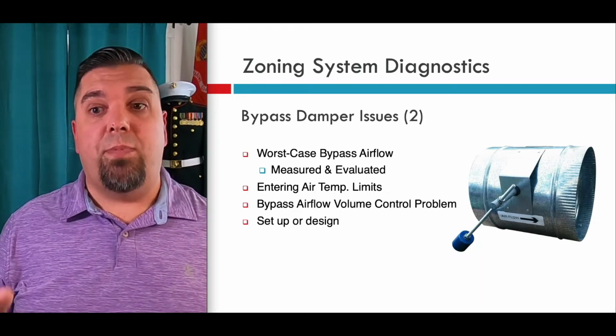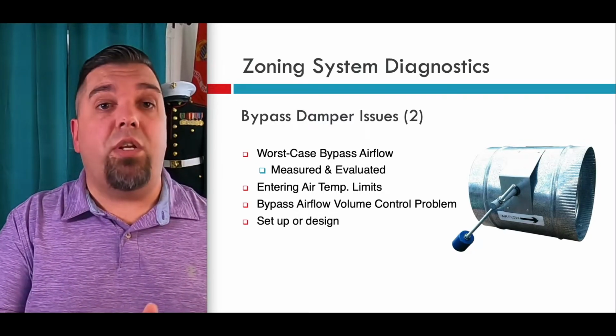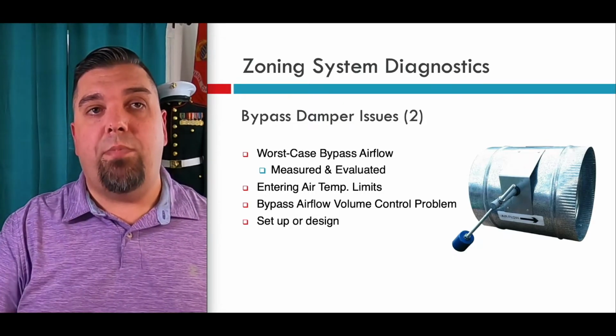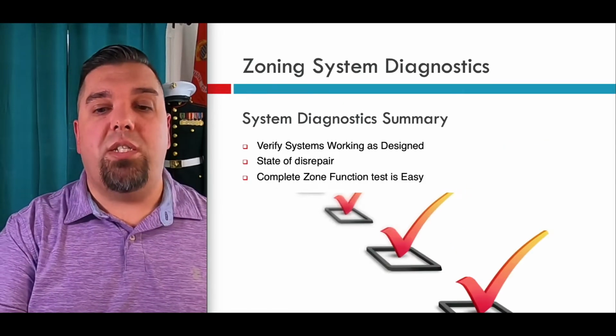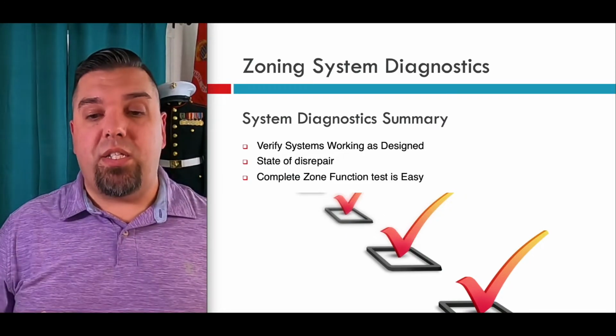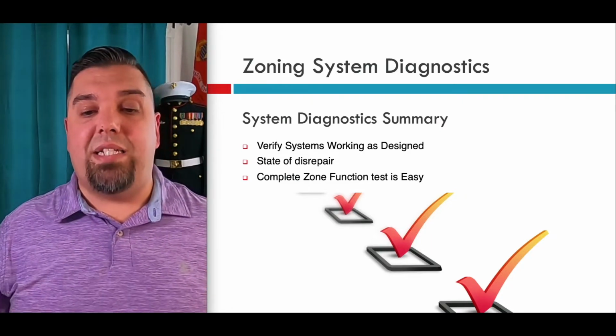That's great, especially if it's made for that particular manufacturer because it communicates well with their heat pump or furnace, okay? If you're retrofitting something and it needs a bypass damper, please walk through the worksheets in Manual ZR, all right? Obviously, after you set the system up, you want to verify, like I talked about in the beginning, that the system's working as designed, all right?